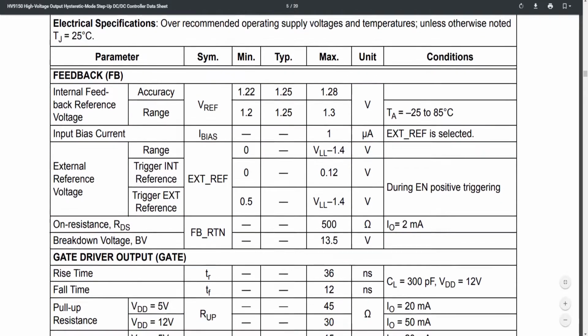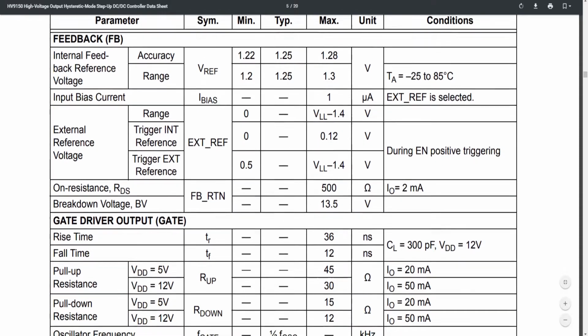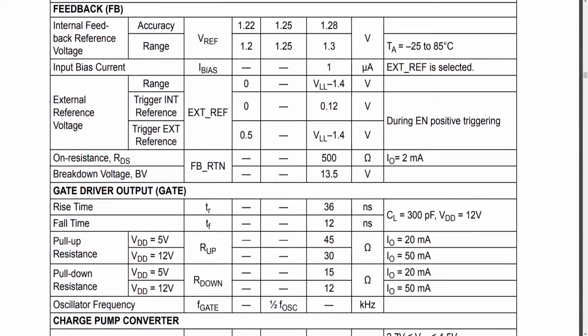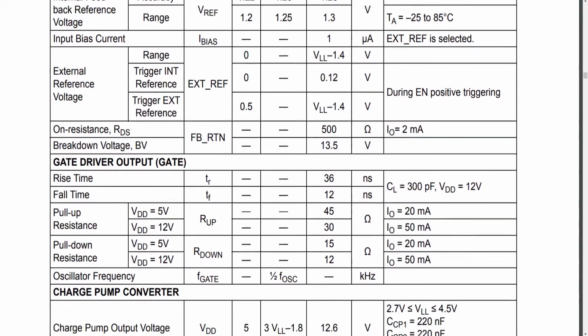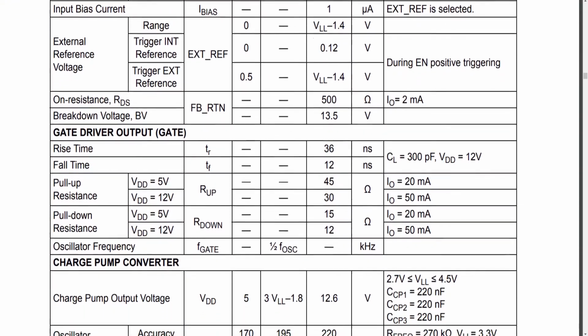They typically do not have a specific control loop, being voltage triggered, or else have an internally compensated loop in addition to hysteretic control. Either way, the manufacturer's datasheet and application notes will often define a range of recommended output filters. Always stay within your manufacturer's guidelines.